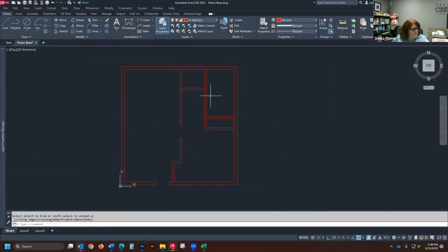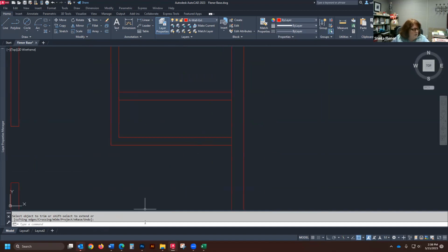All right, so let's make the opening for our closet. So we want 2 sliding doors, each 24 inches in width. So we need a 48-inch opening. So we're going to draw a line from the inside of the closet, not the outside, because it gives a different midpoint, see? So inside of the closet, click, and then go down, click, and enter.